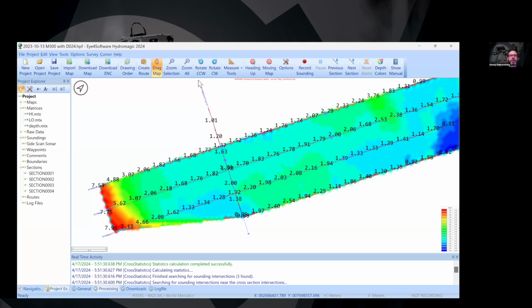Excellent question from Prosper. Has there been a solution to PPK processing with regards to the usage of the M300 drone? The answer is no, without additional equipment. Unfortunately, M300 and M350 drones support PPK mode, but only if you use DJI payloads like L1, P1, DJI cameras or DJI lidars.